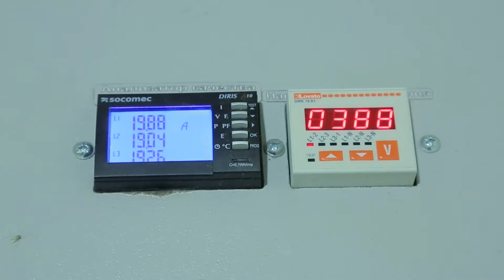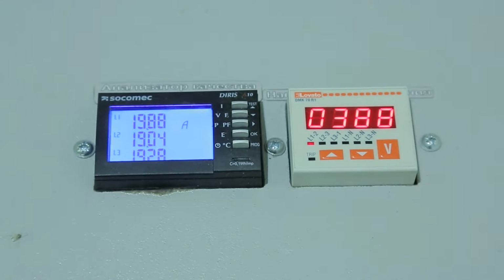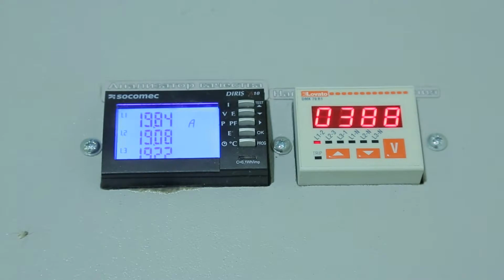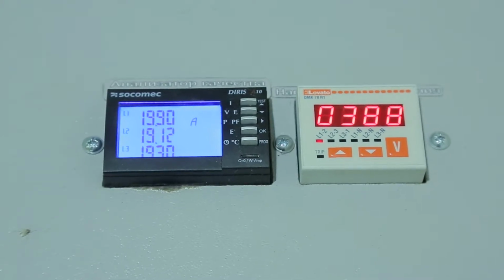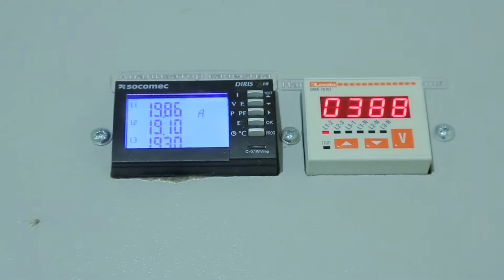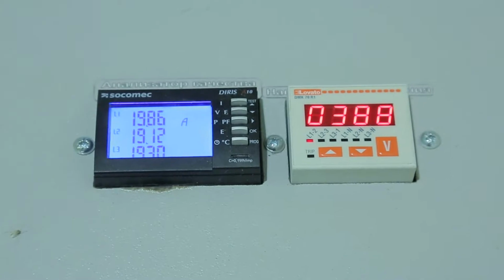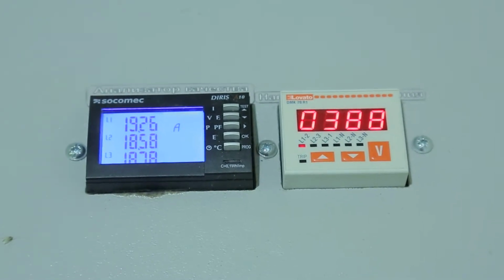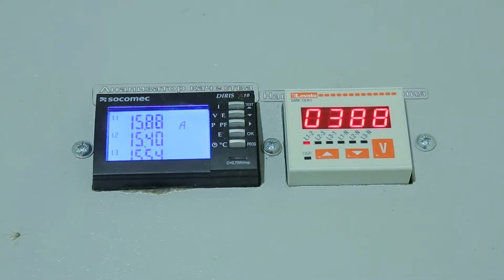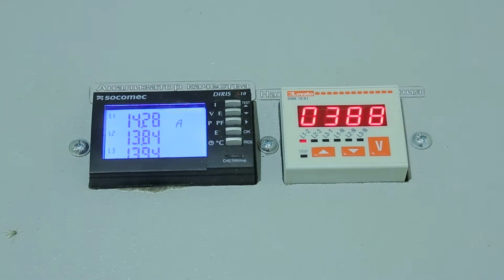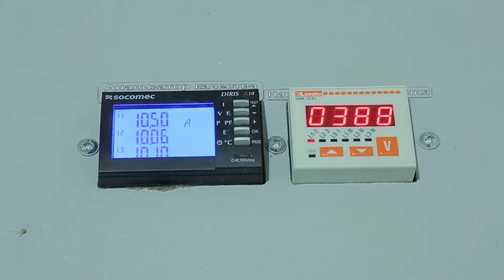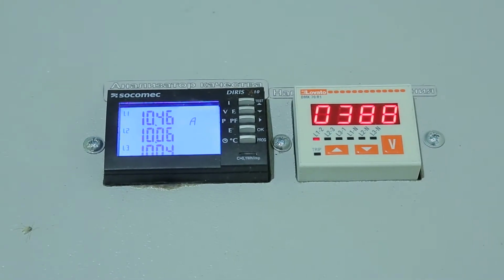The currents and voltages are observed in the stable operation mode of the motor. The device analyzes the induction motor and during 30 to 35 seconds lowers its power without changing the number of rotations at the shaft. The lowering of the working current of the induction motor with a power of 18.5 kW is observed. The total economy of consumed energy at idling reaches 50%.